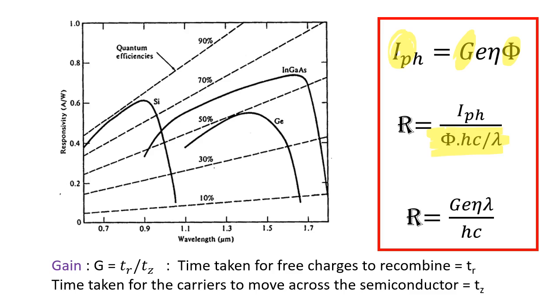So as I mentioned, silicon has a certain band gap. That would mean that this value would correspond to roughly the long wavelength cutoff. Similarly, for germanium, this would be the long wavelength cutoff. You can also have combinations of materials like indium gallium arsenide. We will talk about them. We will see that silicon is an indirect band gap material. So it is not necessarily used for generation of light, but it is certainly used as a detector,